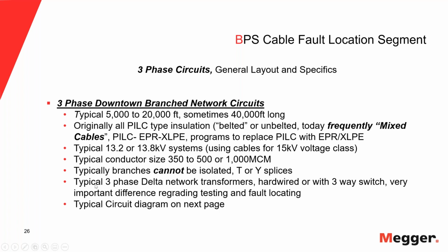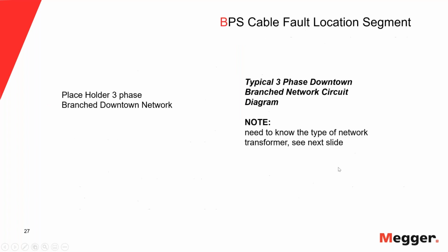In addition to it, we also have most of the network transformers that are used are delta transformers. And again, they could be hardwired or they could have switches in them. And I talk about that in a moment a little bit more. But whether they are hardwired or they have switches, again, makes a difference what we can do in terms of fault locating.